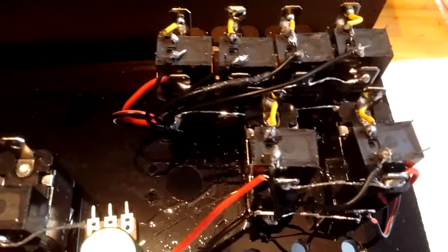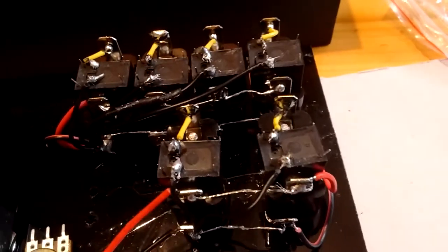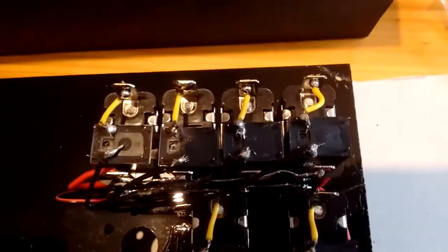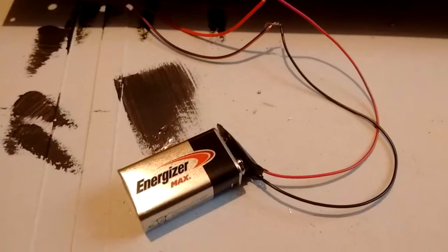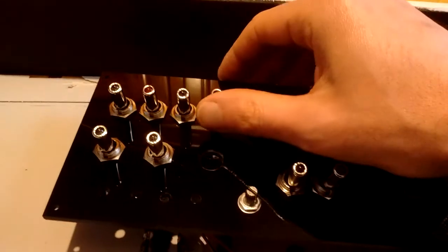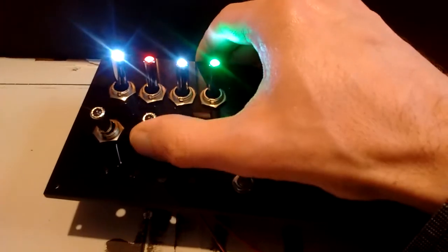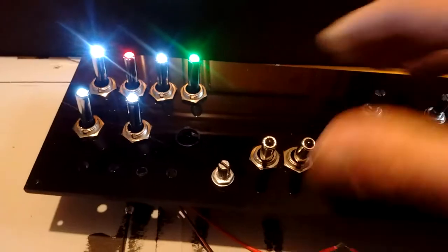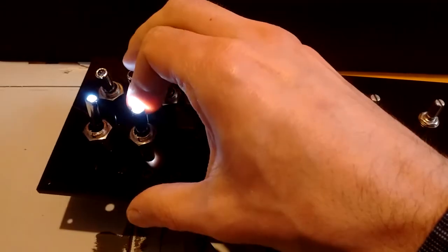So this is the first solders. I've put a red and black wire on the plus 12 volts and the ground, which are soldered on the side of the switch. I've also soldered the wire to the coil of the relay. I now use a battery to check if all the switches illuminate correctly, which is the case. The only default I've found on the switch is that they are a bit difficult to manipulate.